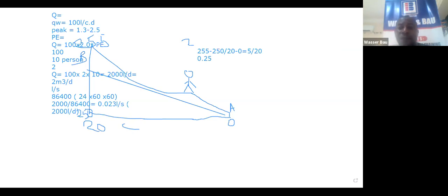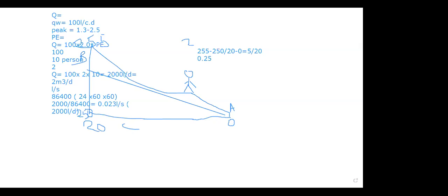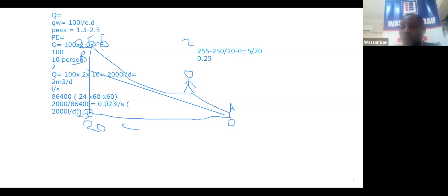So the safe depth is between 0.6 meters and 1.2 meters. So if you are crossing a road, you go as deep as 1.2 meters. But if you are going through a bush part or a normal part, 0.6 is efficient. Then again, if you are going towards where they are going to have a lot of field work, you might also consider going deeper, maintaining at 1.2, so that if they are doing bush burning or any activity on the surface, it will not affect your pipe down.